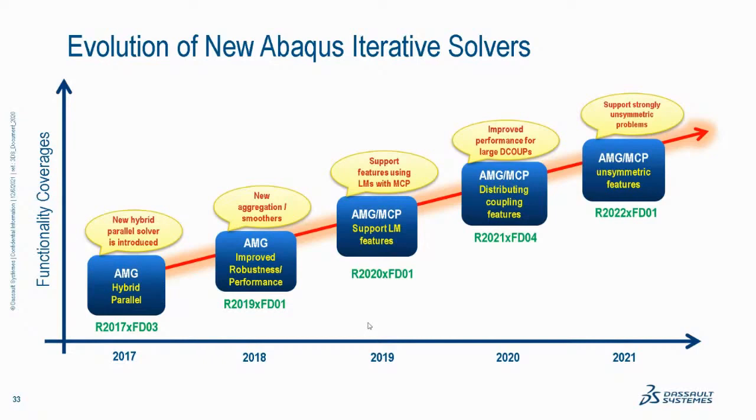It's robust, it's fast, it works for sparse problems very well. But if we have very large models with large memory requirements, blocky models, Iterative Solver is really an enabling technology for those types of problems. We introduced a new Iterative Solver based on the AMG algorithm back in 2017. So fully hybrid, so hybrid execution as I've described earlier. And over the next couple of releases, we improved the performance of these solvers, particularly with things like preconditioning and various other proprietary algorithms in many cases to improve the convergence behavior of the iterative solution technique.